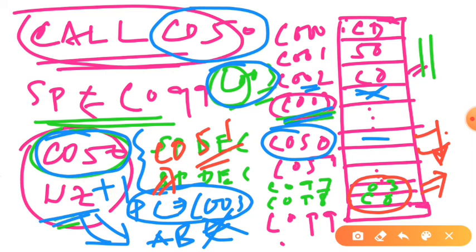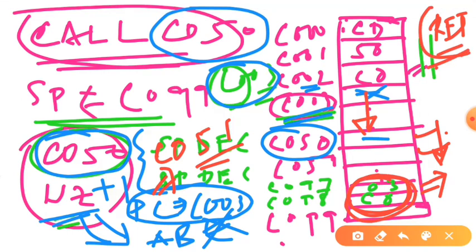So if we use the return instruction after writing this, then the return instruction will fetch this particular memory address from the stack memory, and it will set back the original sequence of program execution, that is from the memory address C003 onwards. So for that purpose we must use the return instruction, and the return instruction fetches this address stored in the stack memory. So this is the process of executing the call instruction.